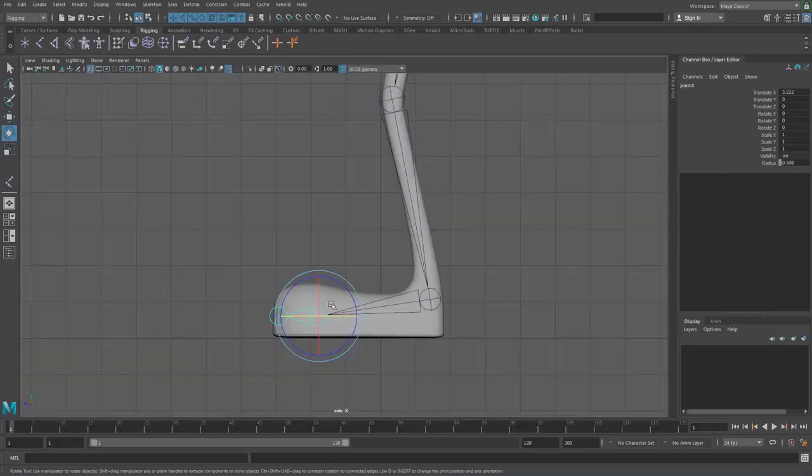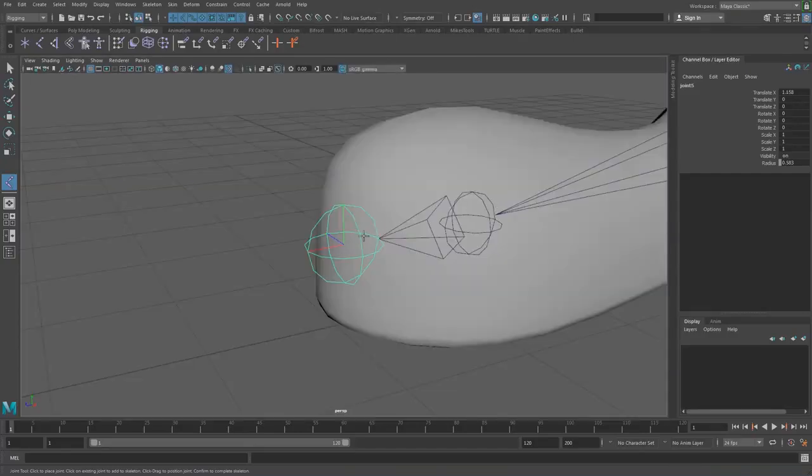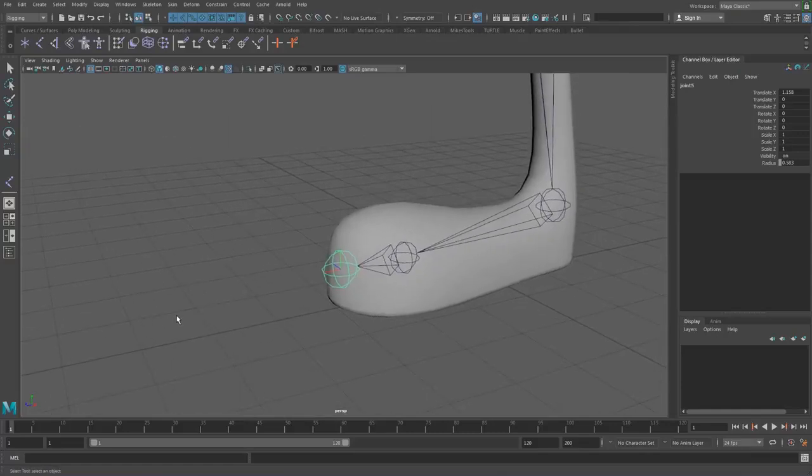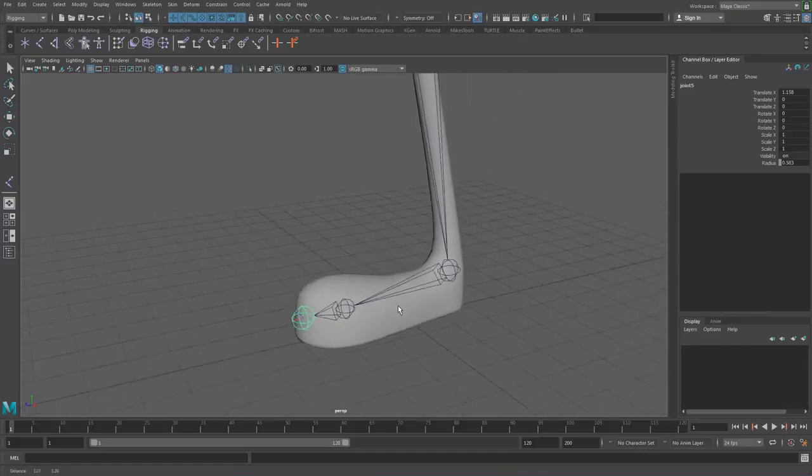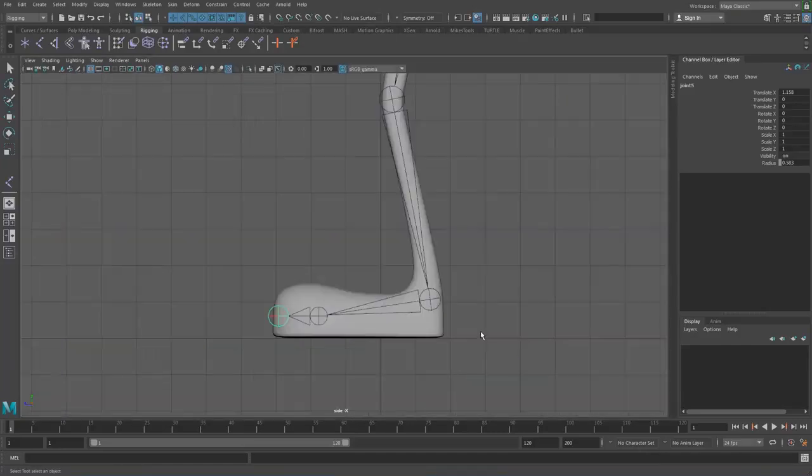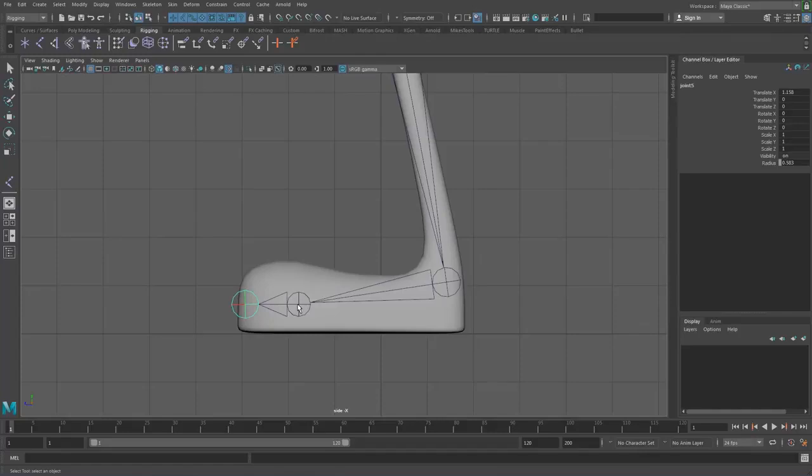So I'm just going to create another joint, and you can do that just by selecting a joint tool and just making sure you select it and then draw another one. And you can see that's reoriented and doesn't look like it's moved much, but if I hit delete, now we can see that that is now pointing in the right direction. So you don't have to keep that new joint that you've just made, but it just sets this up.